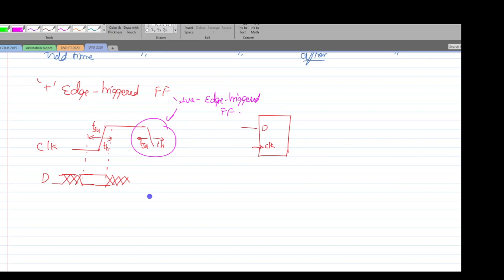Okay, yeah. So since we are concerned about the positive edge triggered, I have to ensure that the data is kept constant or kept stable within this particular time zone. Whenever I have this kind of shuffling of things, it means that I can change my data. Whenever there is no change, no cross marking in these regions, then we assume that the data is stable, and the data could be either 1 or 0. But you cannot switch between two different logic values within this zone. Clear?